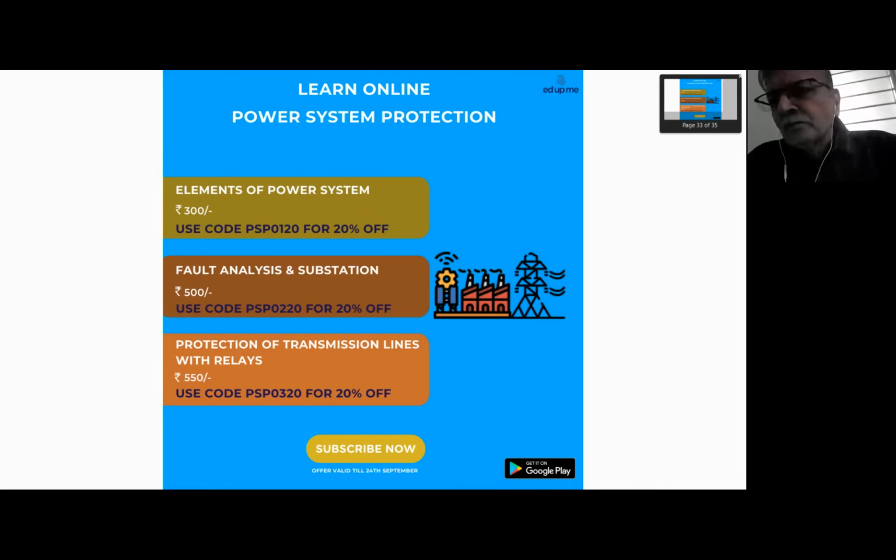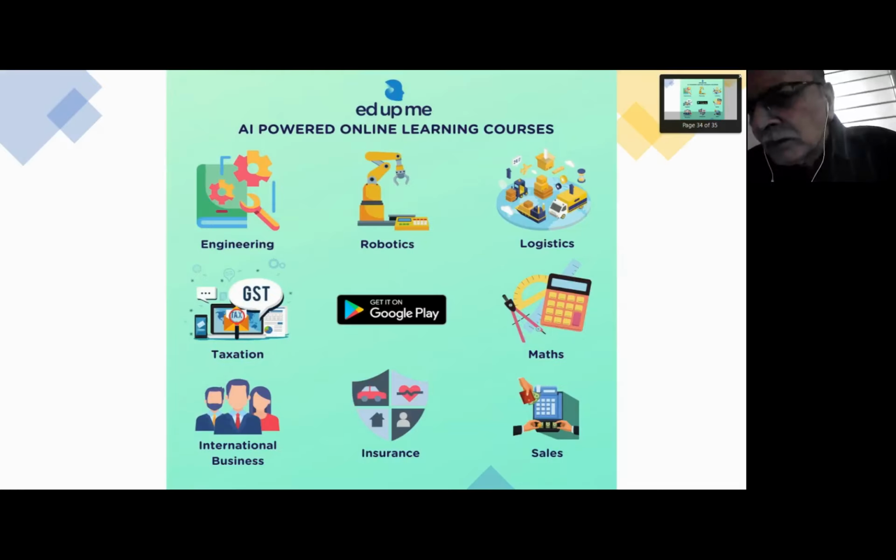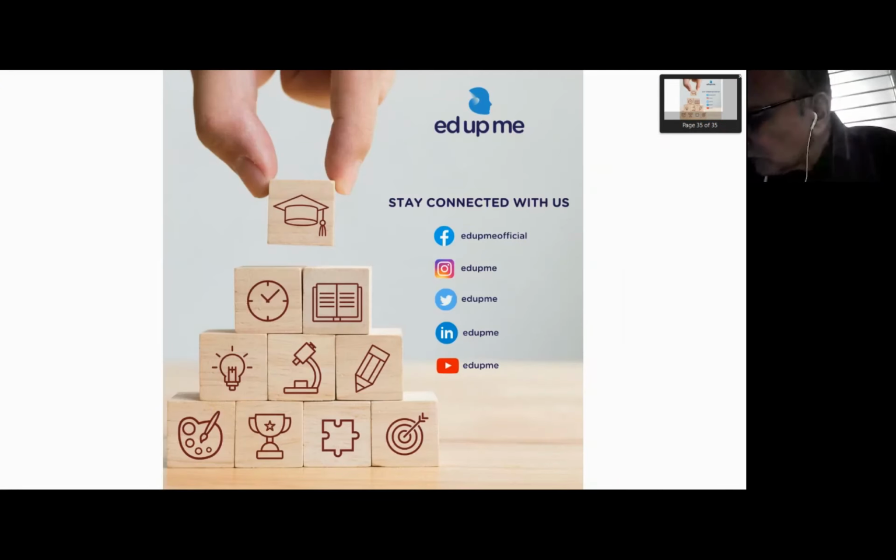Yes, please. There is a question, if I can read it correctly. It says using ZS over ZL or XS over XL is the same for discrimination. I hope I read the right question. Yes, ZS by ZL, that's correct. ZS by ZL or XS by XL can be used for discrimination. That is the question.